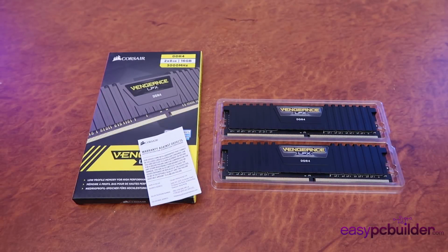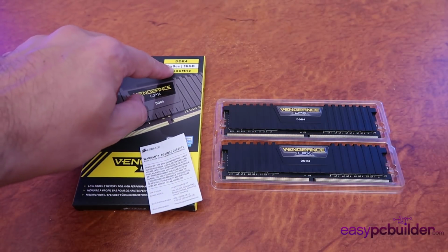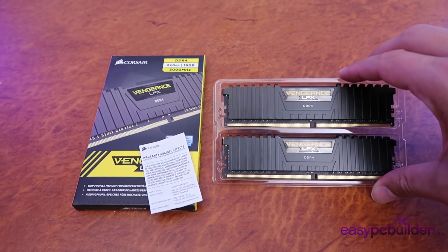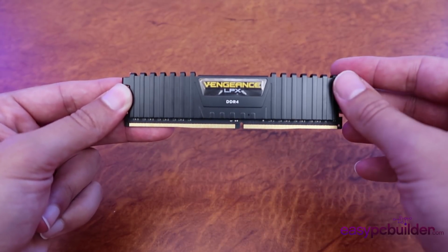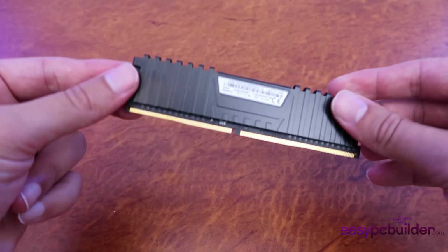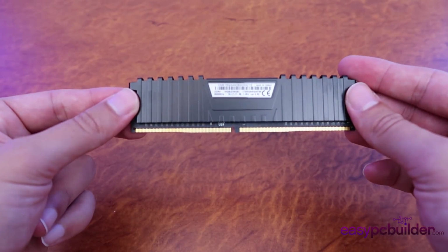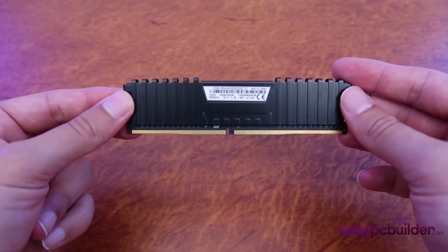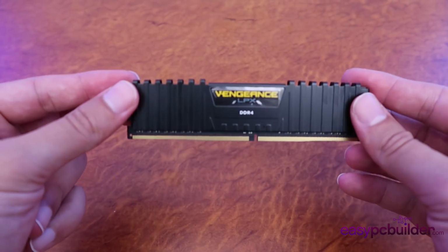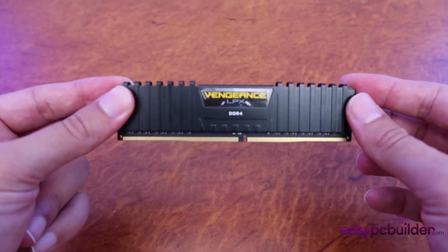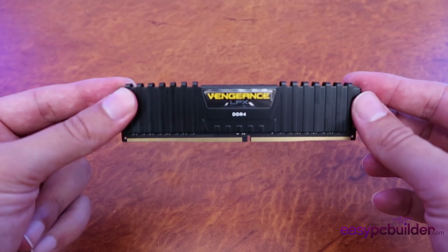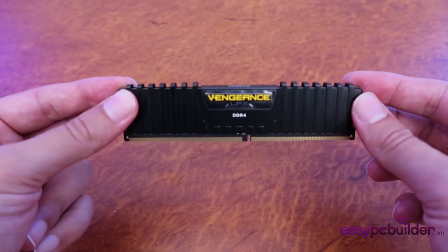So what's in the box when you buy RAM? For this particular model, we have two 8 gig sticks, which are provided each in a stick. Now notice with the RAM that it's notched asymmetrically around the center of the RAM stick. This ensures that you can't plug the RAM stick in backwards to the motherboard, and this notch position changes with each DDR revision or the RAM voltage changes to make sure that you can't plug later model lower voltage RAM into existing motherboards, which can provide a higher voltage or generally be incompatible with the RAM itself.